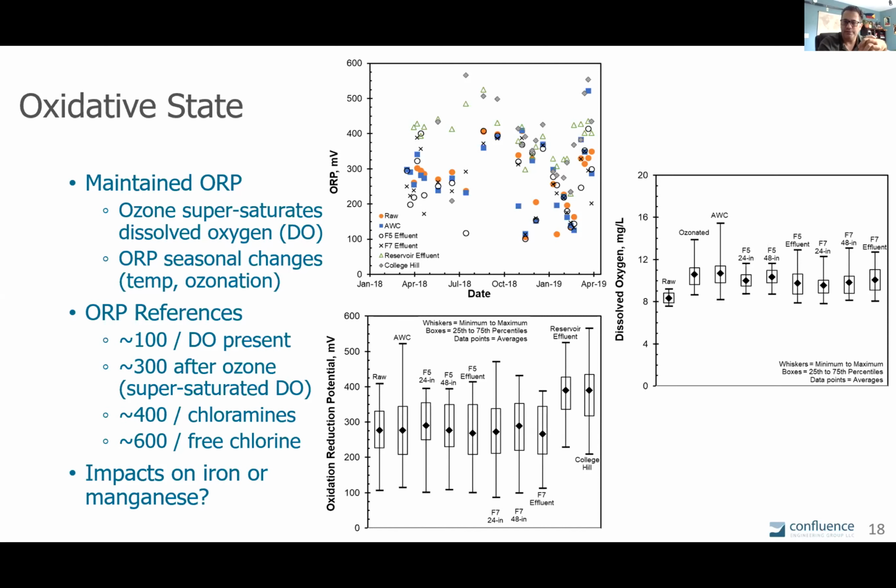Well, we wanted to understand any ORP changes going on at the filters and such because of the potential for iron and manganese change and release. If there was iron and manganese being oxidized through treatment, being captured by the filters and possibly oxidized onto the filters, if there was an ORP change, should they worry about the change in the capacity for the filter to hold that oxidized level of iron and manganese, and would it dump that iron and manganese?